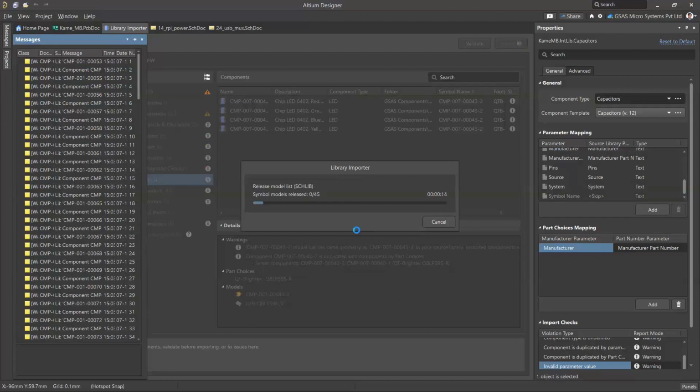This is a very easy and very simple to use tool. There are not many complicated things. Just go to File, Library, in Migrator, and then you can select your integrated library and database library, and then automatically the tool will select the categories based on the component type. It will detect, and if it fails to detect any uncategorized components, like I have shown how you can map those components, we can do the same, and then just click on validate to check if there are any issues with the components or any duplicate components available inside this workspace, which can be shown here.